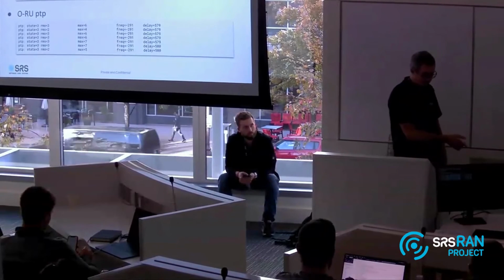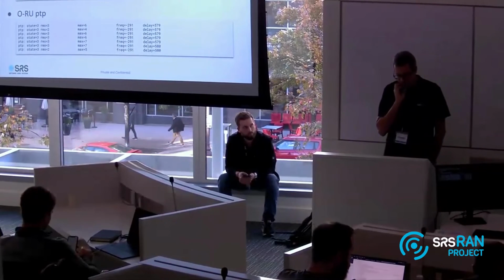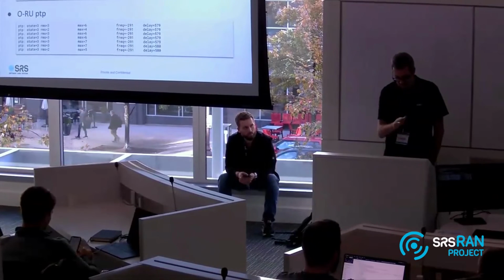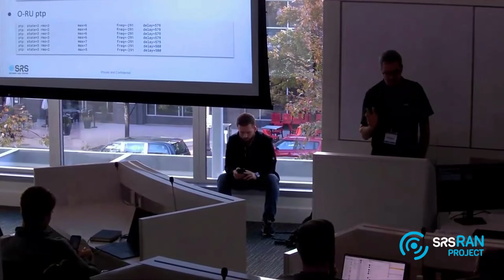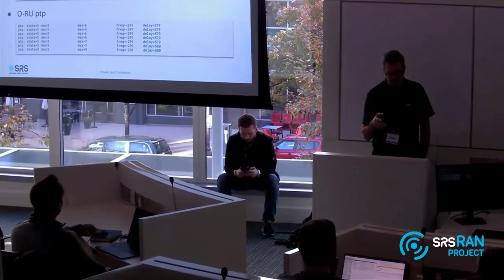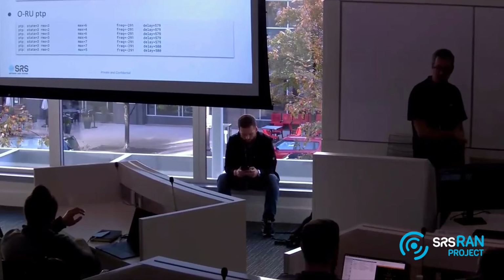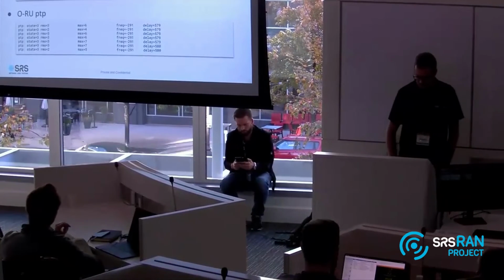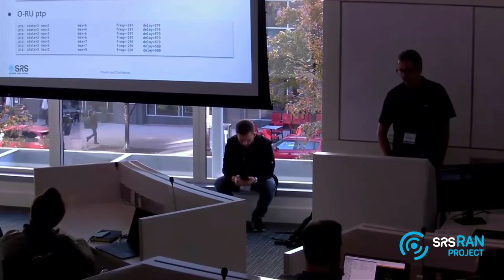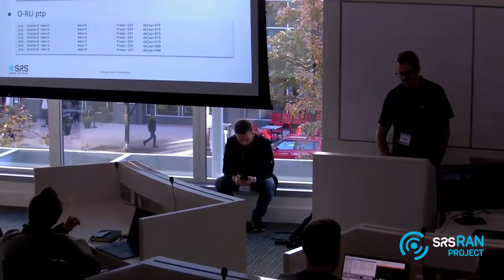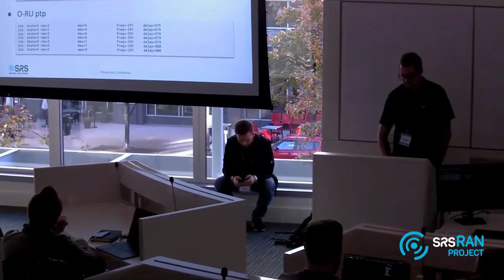You can do this once it's running, especially when you're running with an O-RU. Here I will go through a little bit of a checklist. Most important is to check the timing. Check the PTP at both the DU side and the O-RU side. The command to get this information depends on how you have installed PTP, but typically it's written into a log file.